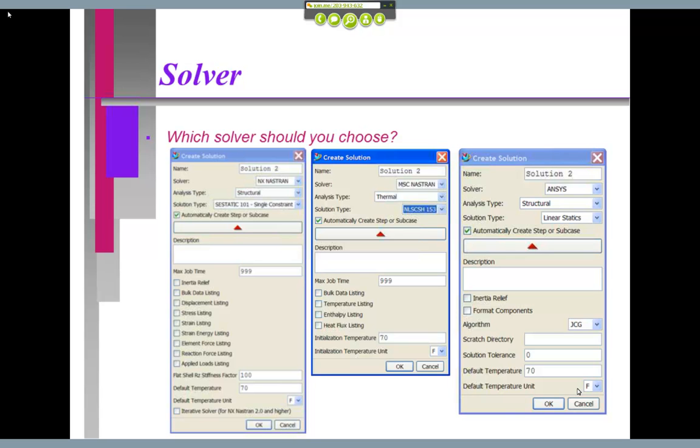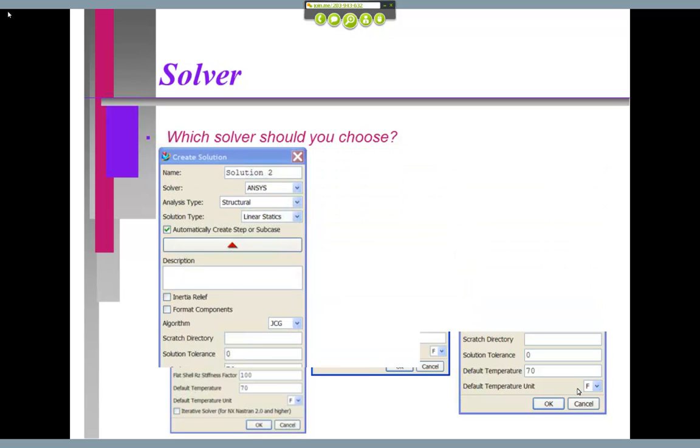What's really nice about it is from inside the CAD system, you can do your meshing, you can do all your pre-processing, and then you just say, go off and use ANSYS. And if it knows the path where ANSYS is, it'll run off, do the solution, and bring back from ANSYS the image that needs to be painted up and displayed on your system. So you can actually stay right inside your CAD system to get the solution.